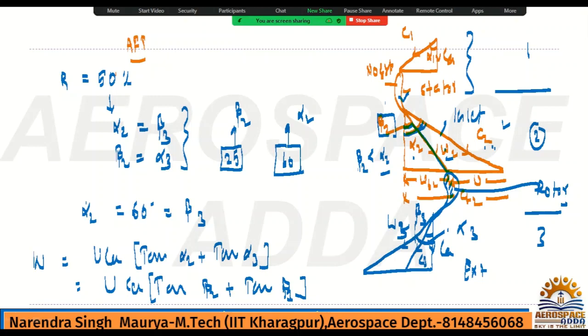Just like in the compressor I had given the velocity variation, similarly in the turbine also we have a velocity variation. If you check, before entering the rotor the relative velocity will be less in the turbine, but once the flow passes over the rotor, the relative velocity will be increasing. Why? Because the flow will hit the turbine blades, and then it will start rotating, right? Initially the rotor is in a stationary condition, you can think, and the flow is coming with very high speed.